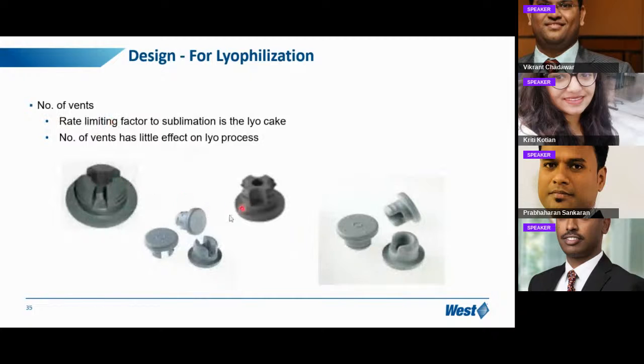And the number of vents. Like I mentioned, there is one-legged, two-legged or three-legged. The number of vents is not a rate limiting factor to sublimation in the lyo cake. So even if it is an igloo design or two-legged design or three-legged design, this is not a rate limiting factor in the sublimation in the lyo process. So the number of vents has little impact on the lyo process.